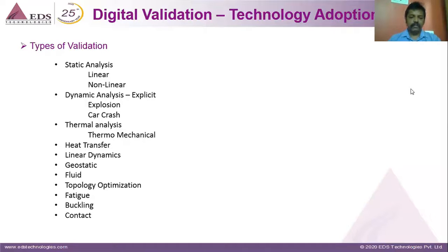Next is topology optimization, where you have a component. Let's say you consider a lower arm of an automotive. So the weight of that particular component, for example, if it's 10 kg, I would like to go with topology optimization. I would try to find out which are the zones which are not actually participating in the transfer of load, and then that particular zone which is not contributing to the stiffness can be removed. So that is how you try to make an organic shape, and then that becomes your topologically optimized shape. So best example is our human bone. You can just try surfing online on this topology for further information.